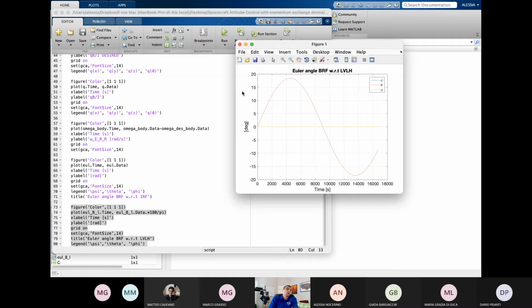The one thing that you can play with, now that you have it working, is to keep reducing that 0.9 coefficient on the initial motion until it breaks. It's basically seeing when things are not linearizable anymore. What's happening is that the LVLH is fast enough for your angles to grow outside of a linearization interval, and so the analysis doesn't apply anymore. Make sense?